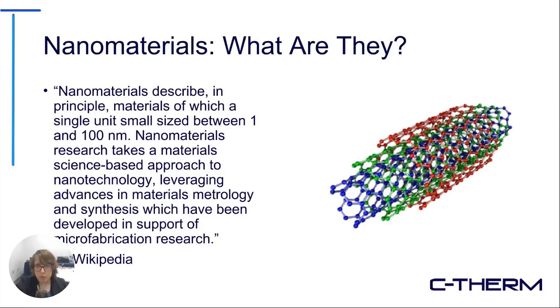So as an example, one would typically think of something like a plastic material, like a polyethylene material, as having a quite low thermal conductivity. You'd expect it to be fairly thermally insulative. However, a single strand of a polyethylene molecule, rather, actually has a fairly high thermal conductivity along the chain.